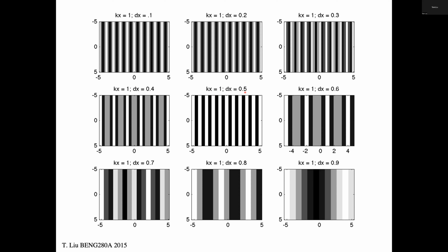After you go beyond this and you start sampling at lower frequencies, interesting things start happening to your function. It starts looking like a much lower frequency function, right? And in fact, here we're getting one big cycle of a sine wave, or a fraction of a cycle of a sine wave. So these are all corrupted through aliasing.